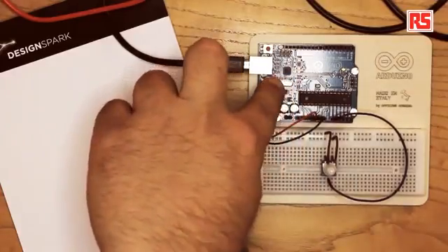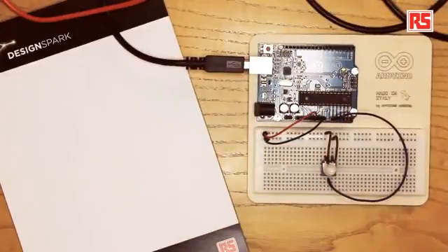For this project, we're going to be using something called serial communication, because the Arduino will send data over to the computer 1 bit at a time at a certain speed that we will define in software. Then the square chip that you see here will convert that into USB data that travels over to the computer. We have used serial communication in the past in order to visualize the data that comes from the Arduino board within the Arduino IDE.